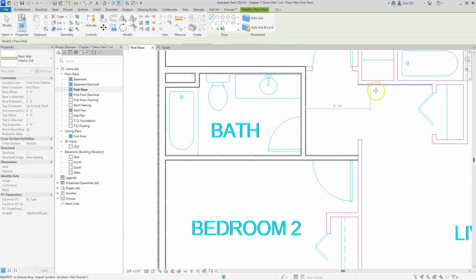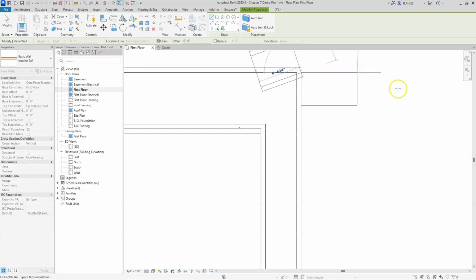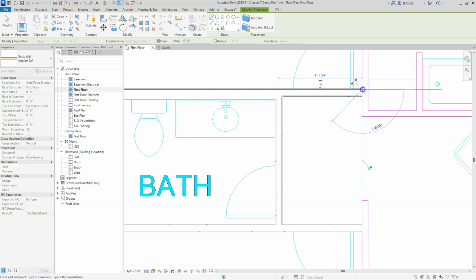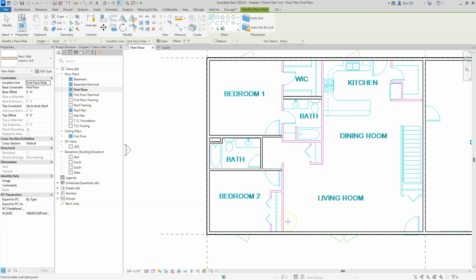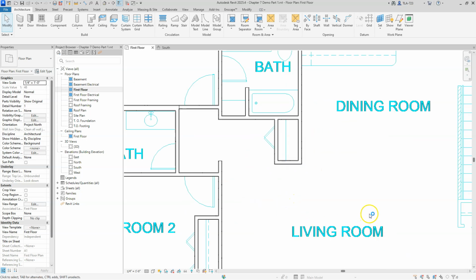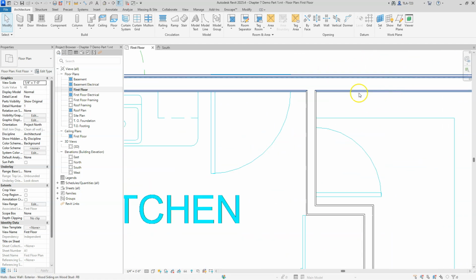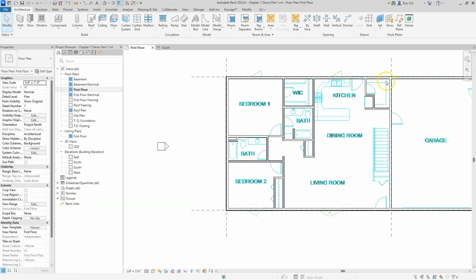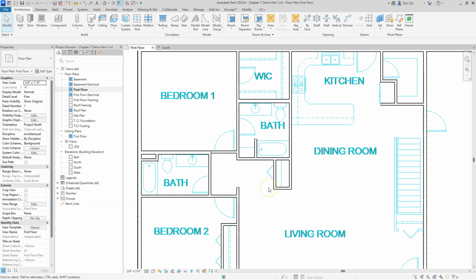So we're basically just creating a bunch of walls without doorways yet. Okay, get in here, make sure that this goes all the way across to here and so forth. So I'm going to let you guys take over from here, but just remember, pass those walls all the way through the doorways. Okay, so when you're all done placing the walls, this is basically what you should see. You're going to see all of the walls interconnecting. They're all going to be joined at the intersections, and you're going to have passed through all the doorways. So obviously the next step is going to be placing the doors and the windows.